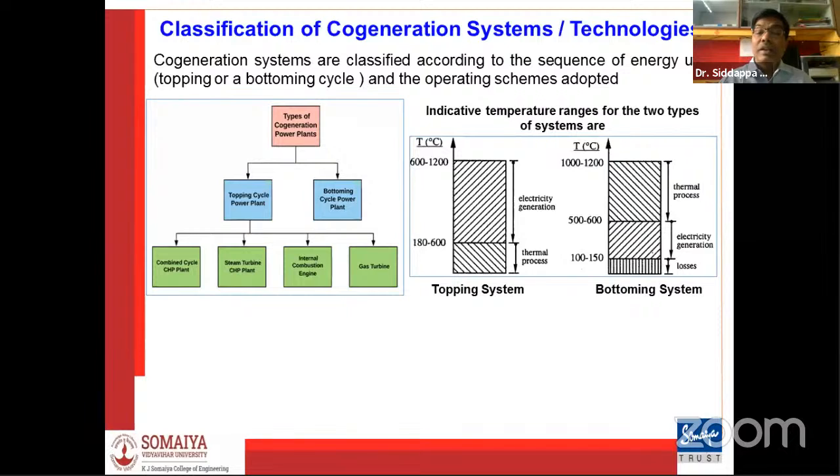I think in so many presentations, the speakers have explained that in thermal power plants we generally have an economizer, then an air preheater, and then again recovery devices for extracting the heat energy. Initially, the high exhaust gas goes to the superheater, then to the economizer, then to the air preheater, and then for small heating applications, and then we expel it to the atmosphere.